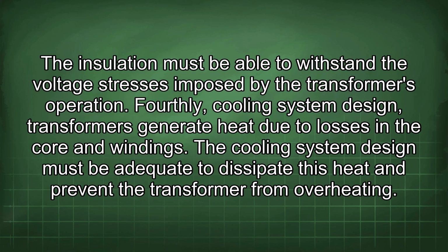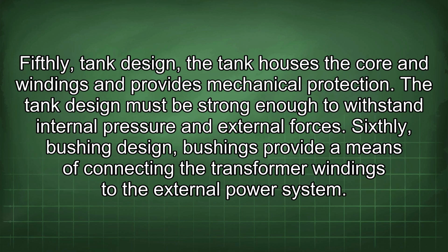Fourthly, cooling system design. Transformers generate heat due to losses in the core and windings. The cooling system design must be adequate to dissipate this heat and prevent the transformer from overheating. Fifthly, tank design. The tank houses the core and windings and provides mechanical protection. The tank design must be strong enough to withstand internal pressure and external forces. Sixthly, bushing design.